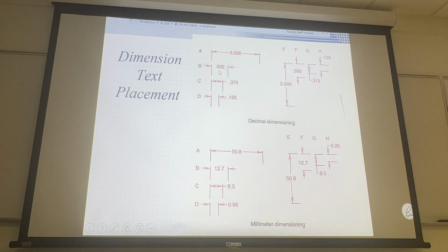Or if not large enough, put the number inside the dimension line with arrowheads outside. Or put the dimension line inside and the number outside. Or put everything outside. Right? It is relatively very easy. When you get a dimension, go to leaders, and you can change all these. The number you can drag.